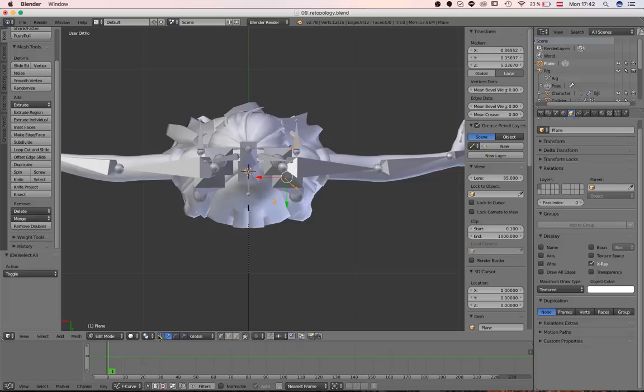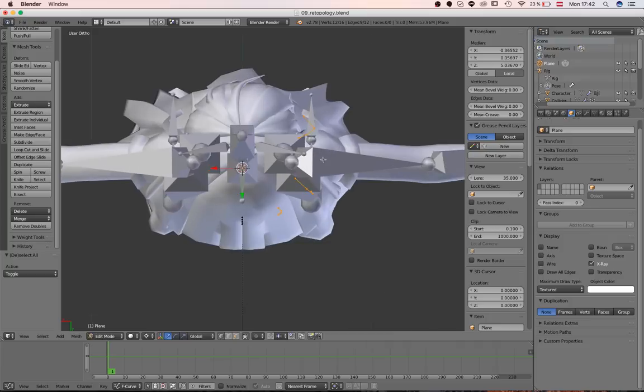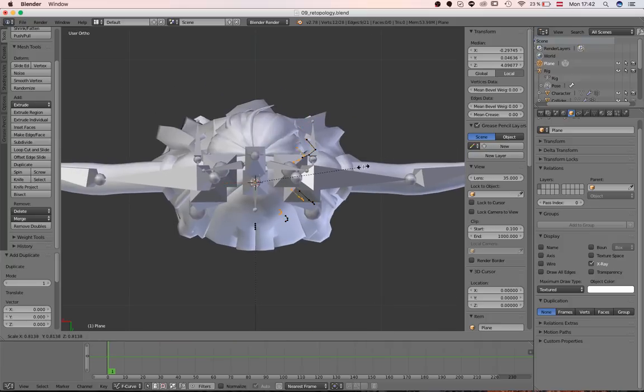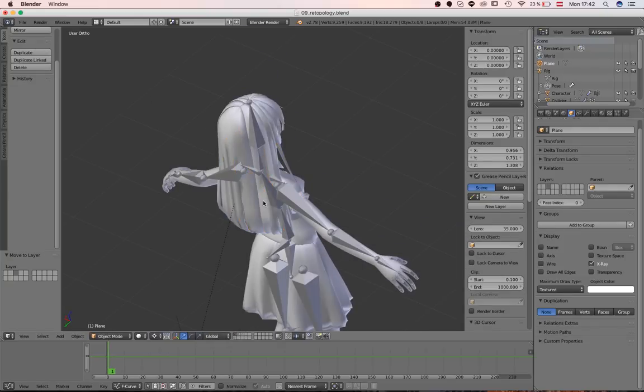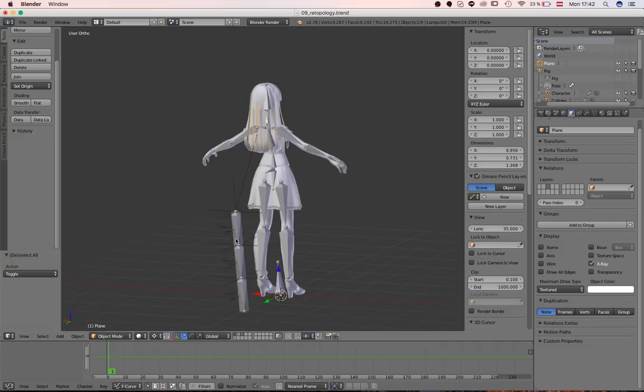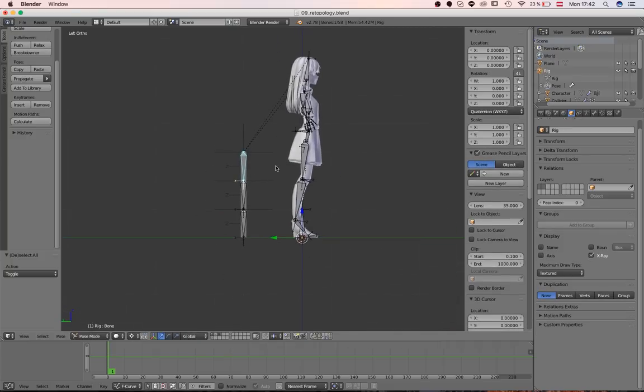By the way, let me quickly flip that. I'll set my transformation origin to my cursor, copy that with Shift D, and then scale it along X by -1. That way, it's mirrored and it's there and everything is good. So I moved it to the third layer,